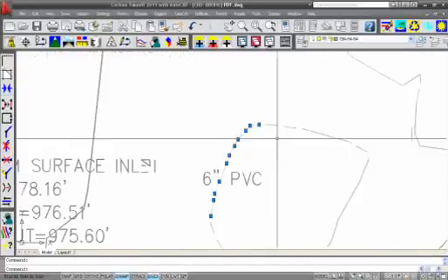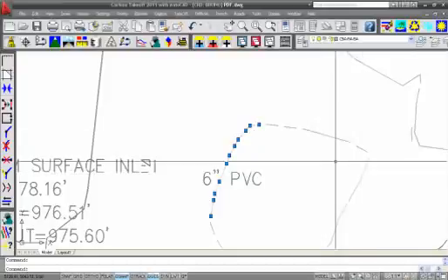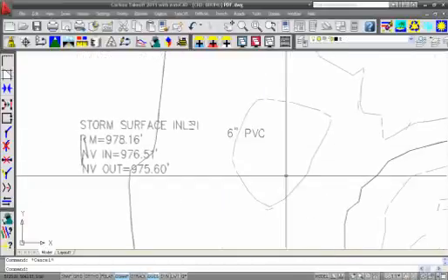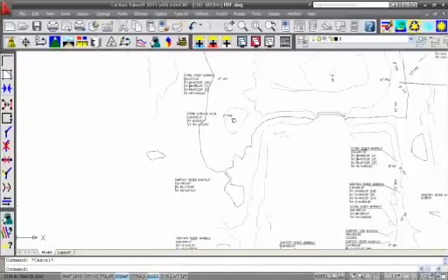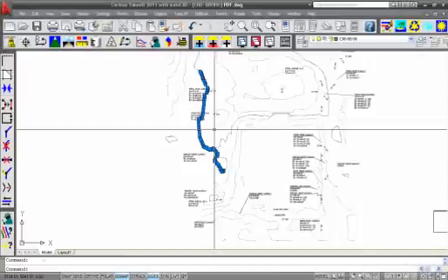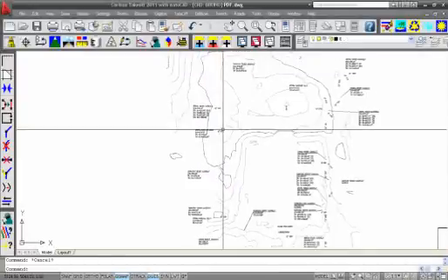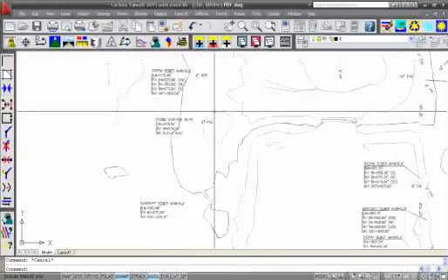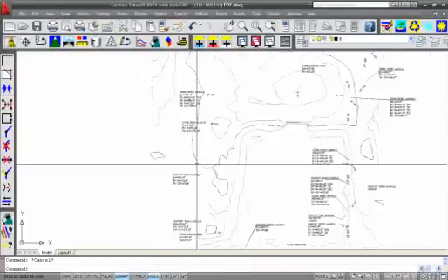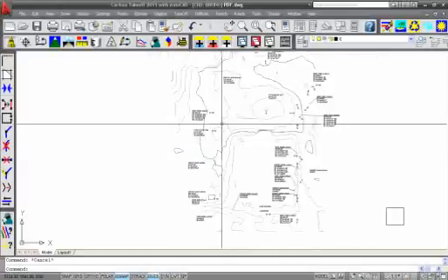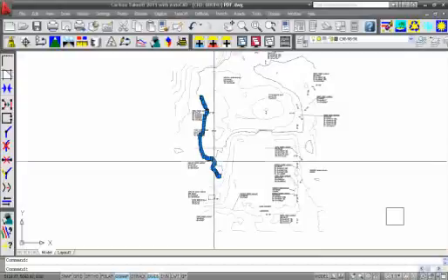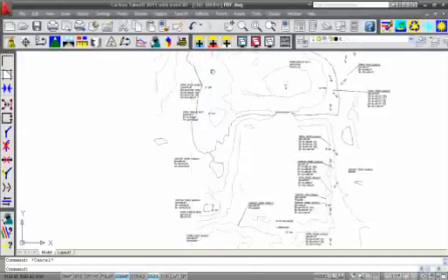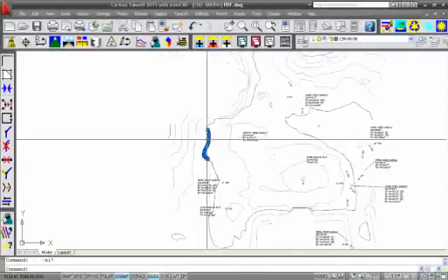You can see it's not perfect connecting all the dashes, but it's a long way opposed to having to do each one. But according to the file, that is a solid line. We're just looking at a graphic array that just hasn't connected everything, or are they still segments? So those are segments in the line. But by doing this convert, it saves me from having to digitize this line in here. Okay.